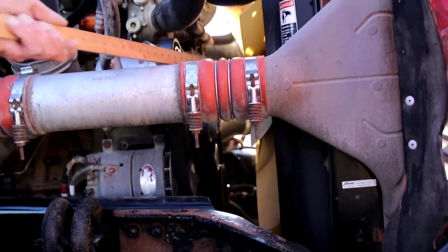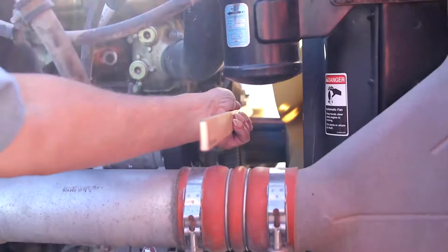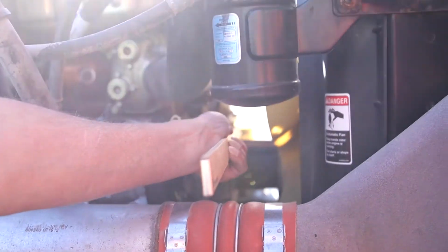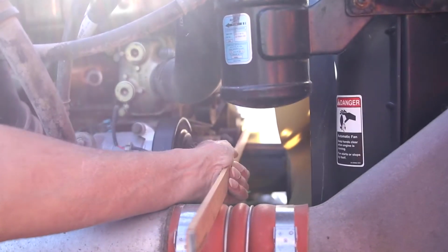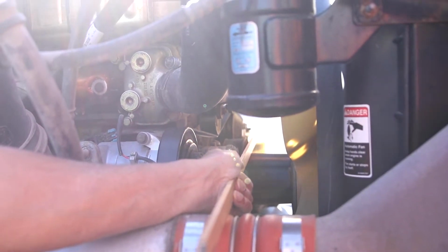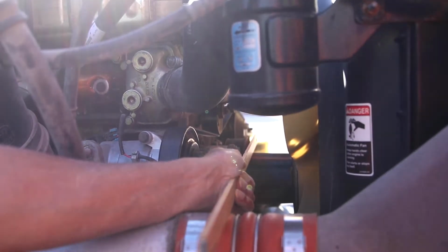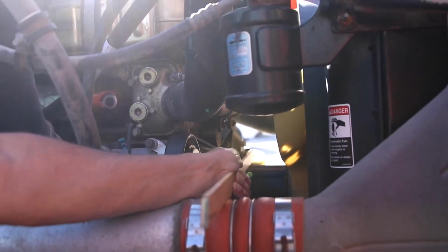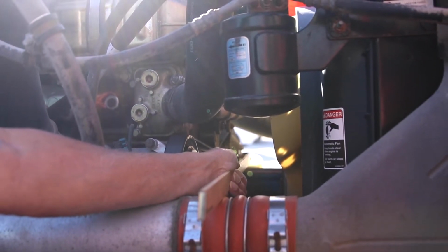Your water pump is located almost directly behind the fan. It is mounted securely to the vehicle. It is not leaking. And it is also belt driven. And the belt does not have any cuts or frays. And again, no more than 3/4 of an inch of play in the belt.